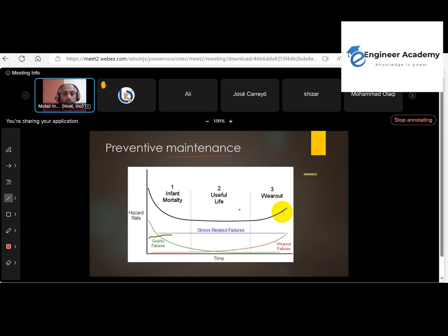Like in some kinds of operation, like in a dehydration package, we found heating and cooling. In this case, this component is exposed to heating, which makes expansion, and cooling, which makes retraction, and so on. This repetition makes fatigue, and of course it will lead to cracks